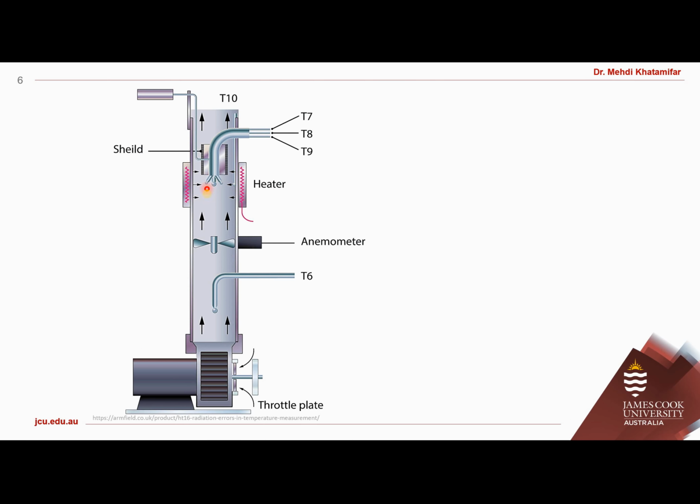So imagine you want to record the temperature of air, as we are recording here, with a thermocouple with, for example, a large bead at the tip, or a small bead. If we had a hot surface around and we had radiation, what are those numbers going to be? Are they going to be different numbers for these thermocouples, or are they going to be the same? If they are different, what are the parameters? Is the emissivity of the beads going to affect the temperature we are reading?